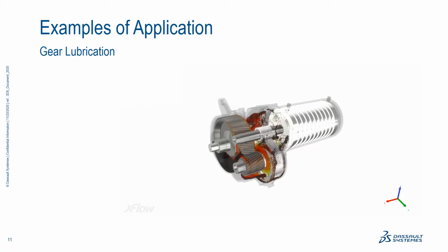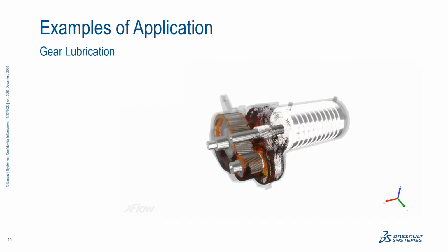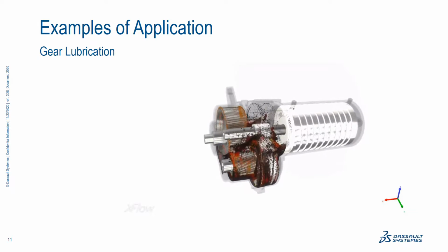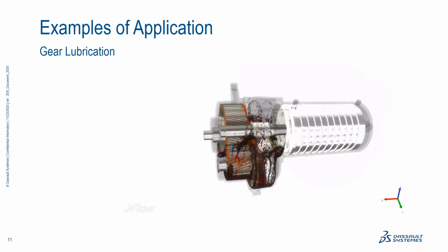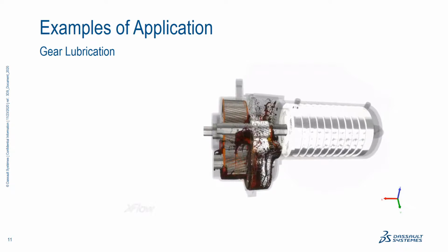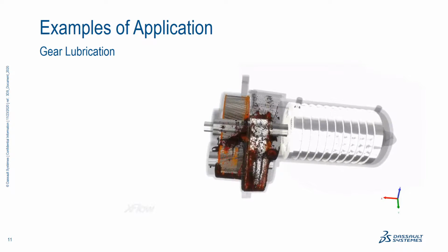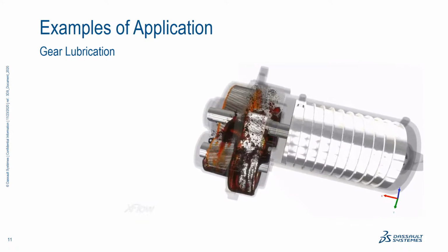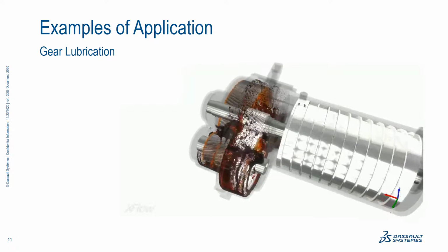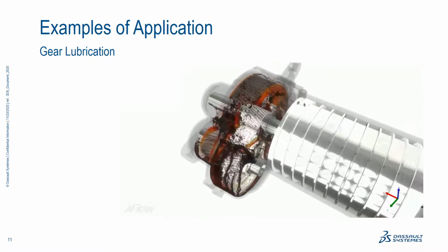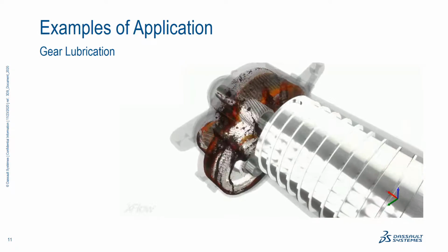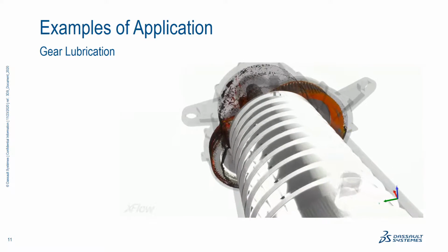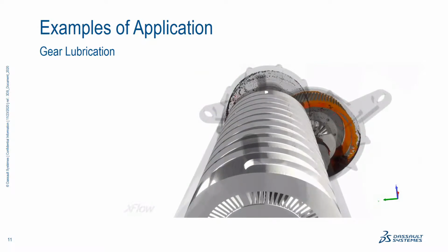The one is the example of gear lubrication. So with Simulia XFlow, we're having a CFD code for multi-phase flow, for open surface flow, etc. It's based on lattice Boltzmann technology, and it's allowing really short modeling times and high fidelity, especially if you're having also moving parts, and especially for a gearbox. Even if you have a prototype, it's really, really tough to actually get any insight on the lubrication if you want to measure it, simply because there's fluid everywhere. So you can't really see anything within.